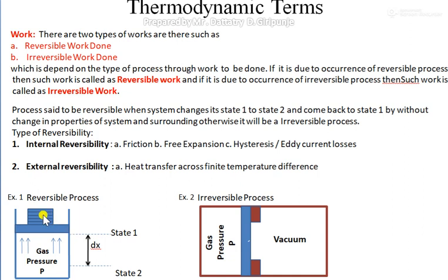Now, whatever weight I have added, when the piston reaches state 2 and I want to move the piston back to state 1, what I have to do is remove, one by one, the same weights I have added over it. So I start removing weight from the piston. Now my piston is supposed to move in the upward direction slowly, and as it is frictionless, the same amount of work I have taken from the surrounding, my system will give back to the surrounding,